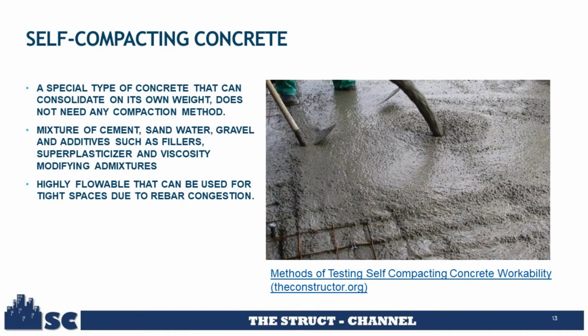Another difference of SCC from normal concrete is that it uses a smaller aggregate size, usually 3/8 of an inch, to achieve a better filling ability. Mineral admixture also improves the viscosity of the base of the concrete to achieve less segregation of the coarse particles.